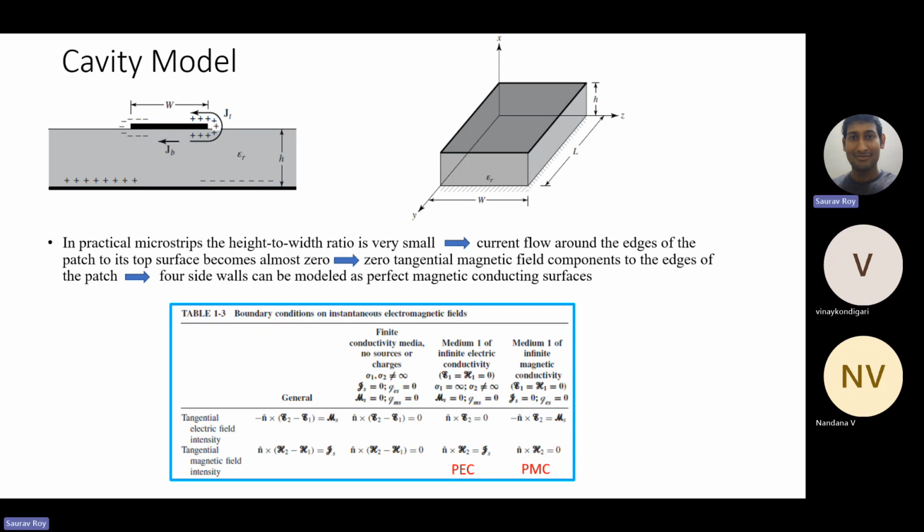Now we saw how it was happening. Because of these charges, there are charges mainly in the bottom of the patch, but the side charges, or J_T, are negligible. Can you visualize this rectangular or cube-like shape on the right side? That is showing the actual cavity: the top is the patch layer and the bottom is the ground layer. In between we have the substrate.